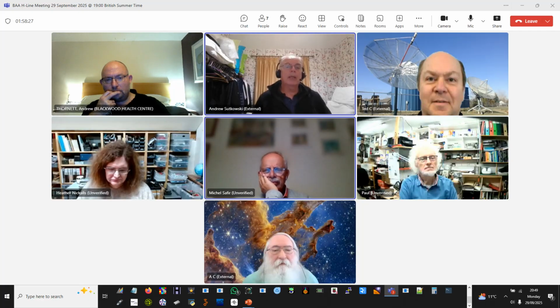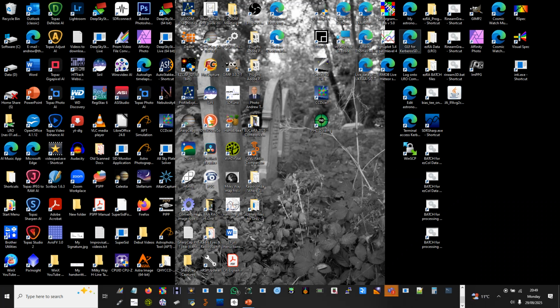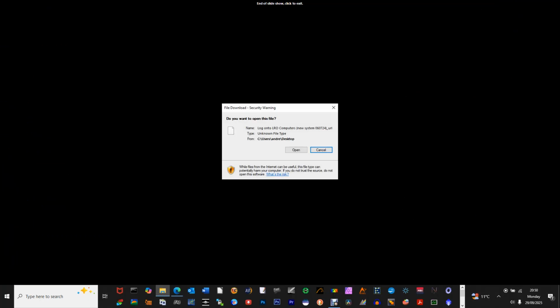So two of them independently into the computer, and then in GNU Radio you take those independently through the FFT, and then after the FFT you can then join them together or record them independently. And in the independent traces there's very little signal if you do it that way. If you use a single Airspy, either on one of the monopoles independently or with the two monopoles joined together, then you get the hydrogen signal.